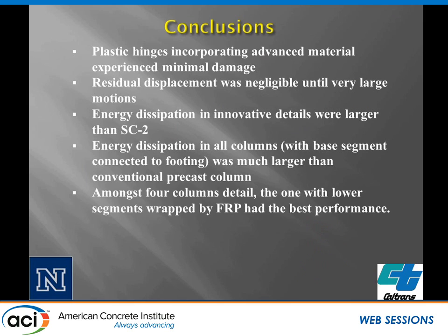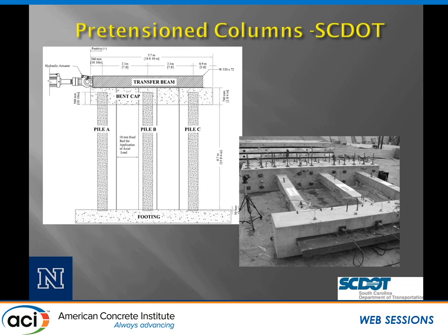Okay, so what's the conclusion that can come out of this? Well, the plastic hinging incorporating the advanced materials experienced, now it says the word minimum damage here, but that was at lower levels, not at these maximum levels. The residual displacements were less, okay? The energy dissipation in the innovative details were larger, okay? And we saw just overall better performance out of these systems.